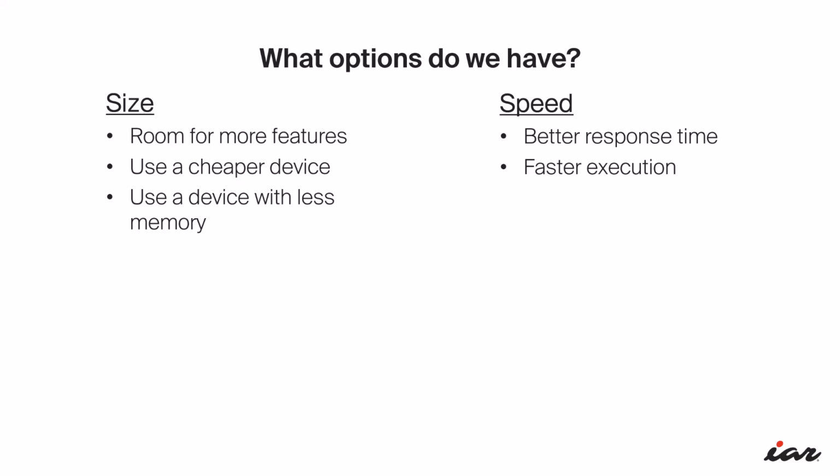And now we are talking about power. So how does that fit? The tools, they can generate code for optimized size or optimized speed, but we are thinking about power here. And as we will see here, power, of course, to saving power and enhance battery time, it's all related to use speed optimizations. You mainly do as fast as what you need, and then the rest of the time you spend on sleep or idle.